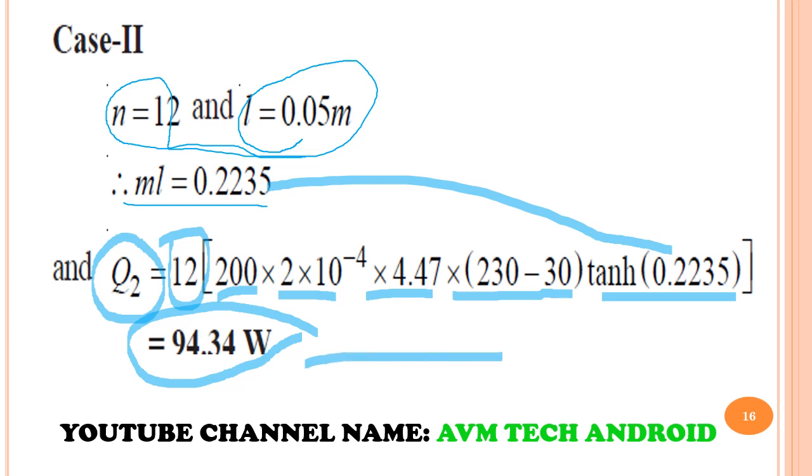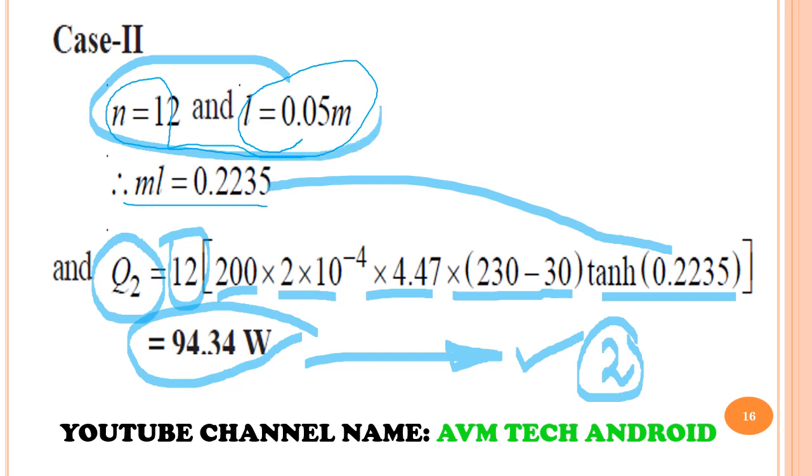So definitely we want to increase heat transfer using the fin, so we have to go for second case. So this is our answer. Instead of going with 6 fins of 0.1 meter length, we have to go for 12 number of fins with 0.05 meter length. So this is our required answer.